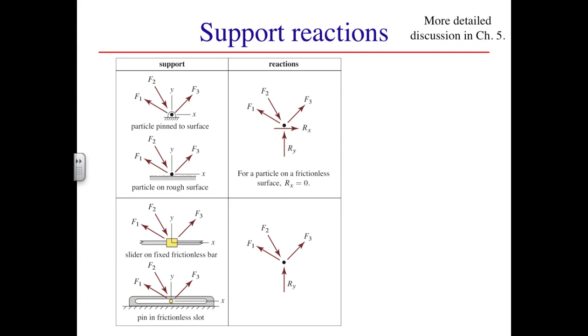In our earlier discussion of pulleys, we talked about the reaction forces that could be developed at the pulley bearing. To identify support reactions generally, we need to first identify the so-called degrees of freedom, meaning translations and rotations, that are prevented or impeded by the supports. For every degree of freedom prevented or impeded, a support reaction exists. At this relatively early stage of particle equilibrium, there aren't that many possibilities, but we'll discuss these four.